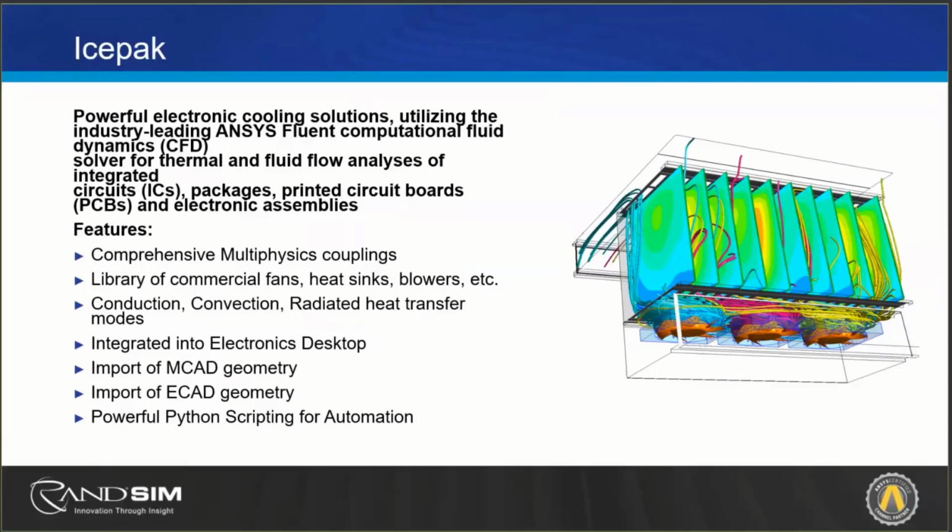The workflow from a step file to bring it into Icepak Classic is very streamlined. You can do it through SpaceClaim, or you can bring it into the electronics desktop, and you can do your analysis within the electronics desktop. So there are multiple ways to use the tool.